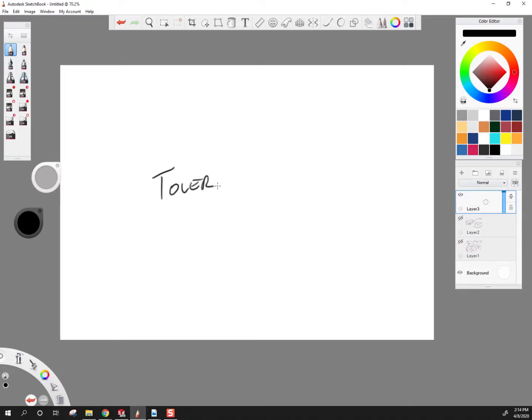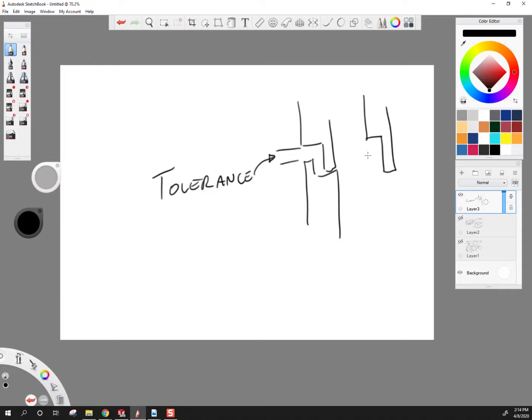So tolerance is the reason why there's a gap there. So in our part line here, this gap is for tolerance, and that is so that the one thing that designers can control is by making one always longer than the other. Even if through tolerance or imperfection this ends up shorter and this ends up longer, they know what the acceptable level of tolerance is always, so that even in worst case scenario,